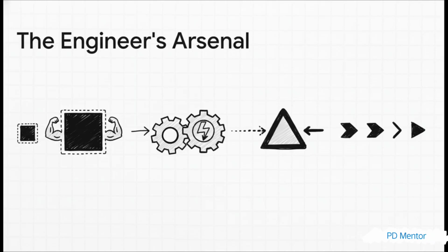So what can an engineer actually do? Well, they've got a whole arsenal of techniques. They can make certain cells bigger and stronger to push the signal harder. They can swap in faster, higher performance versions of cells. They can strategically add those little buffers we talked about to break up long wires. Or they can even add new pipeline registers to break up one long, difficult journey into two shorter, easier ones.